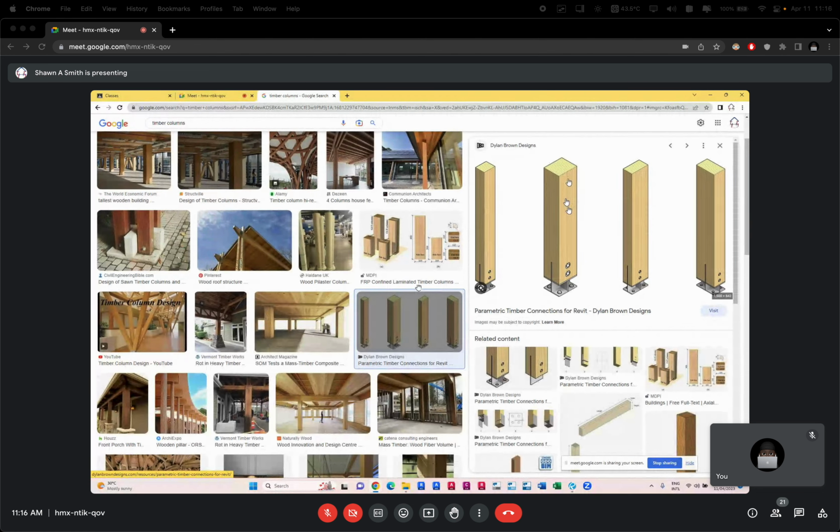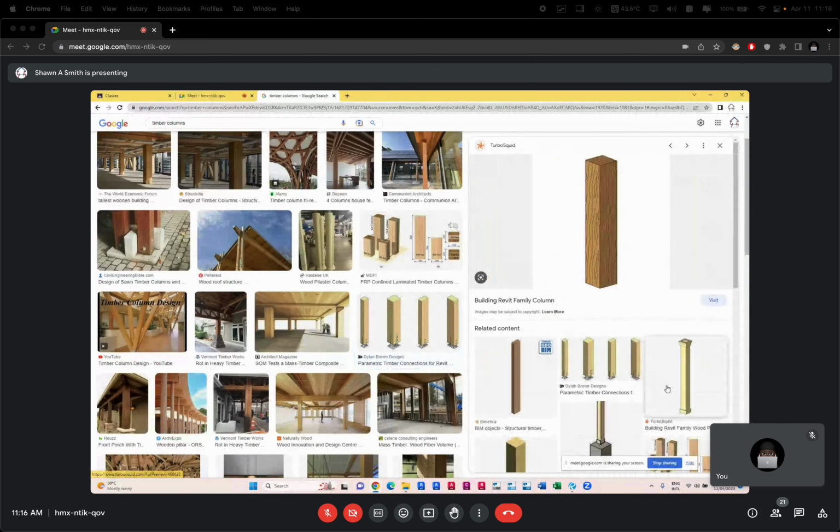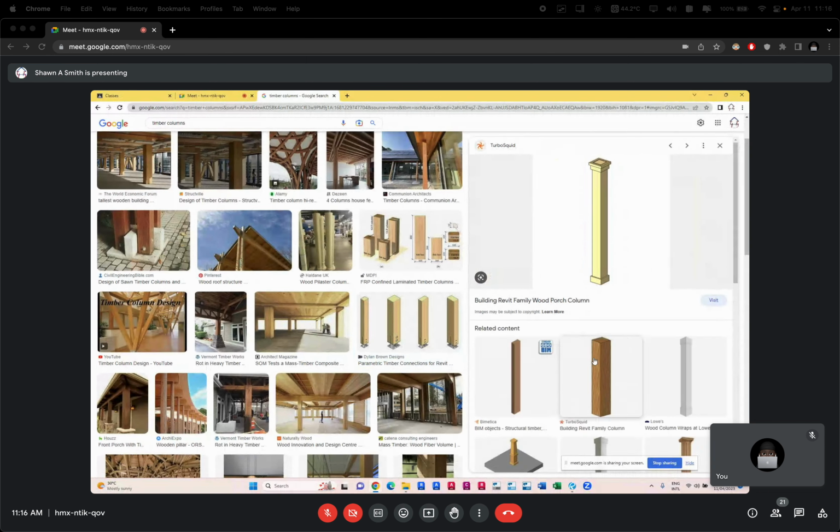We don't try and cut timber where the grains are perpendicular. Only in beams do loads act perpendicular to the grain of the element. For columns, it runs through the axis, so the loads are acting parallel to the grains. All right, parallel to the grains.